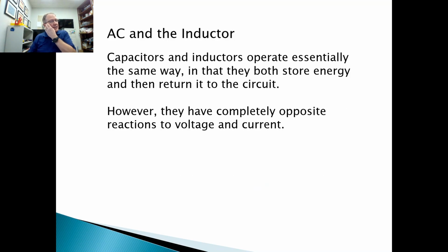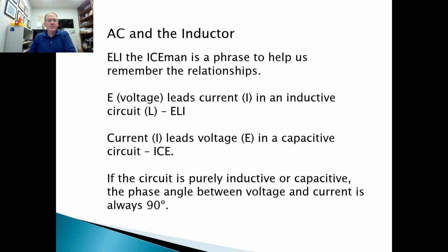Capacitors and inductors operate essentially the same way in that they both store energy. However, they have completely opposite reactions to the voltage and the current. So the term ELI the ICE man is a phrase to help us remember this relationship. E is the voltage, and it leads the current in an inductive circuit.